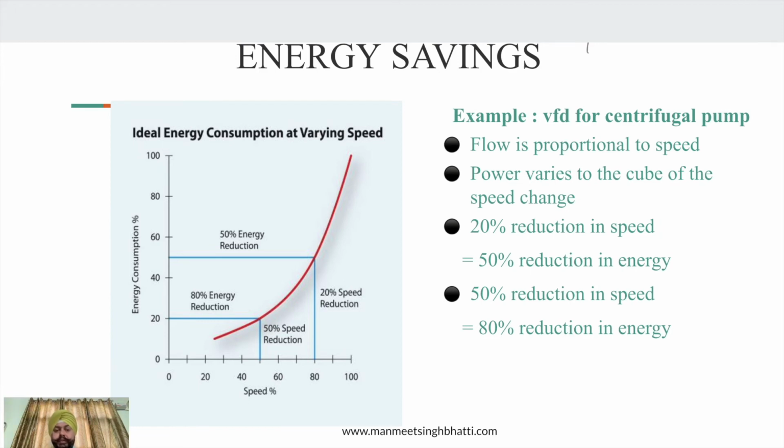In the same way, you also have energy losses, because all the motors are running at maximum speed. You are not reducing any speed, you are not controlling any kind of frequency. So if a motor has, say, 10 ampere current load, it will continue to have 10 ampere current load irrespective of whether you are crossing the pressure threshold required at the end. So putting a VFD in the complete system gives you two things. First of all, it is going to control the amount of pressure which is required at your farthest end.